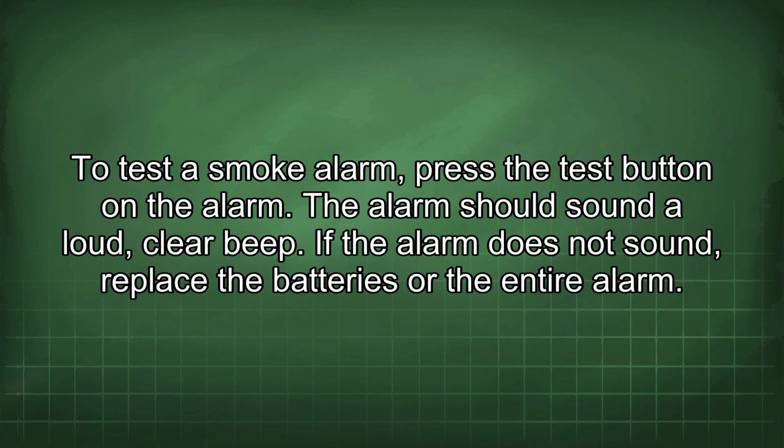Smoke alarms should be tested monthly to ensure that they are working properly. To test a smoke alarm, press the test button on the alarm. The alarm should sound a loud, clear beep. If the alarm does not sound, replace the batteries or the entire alarm.